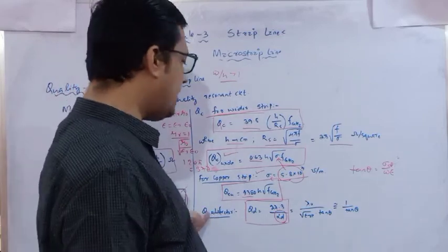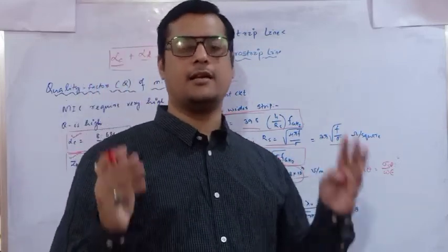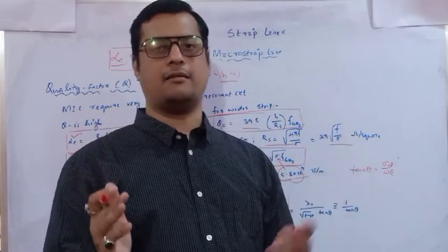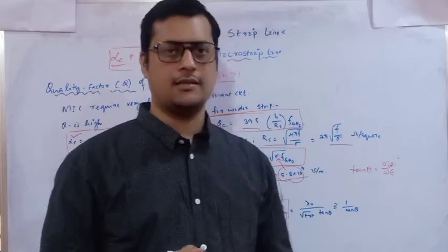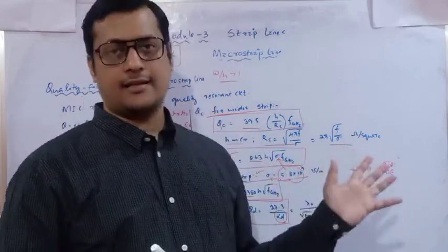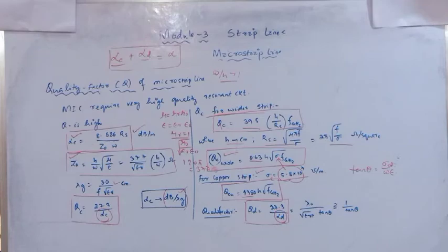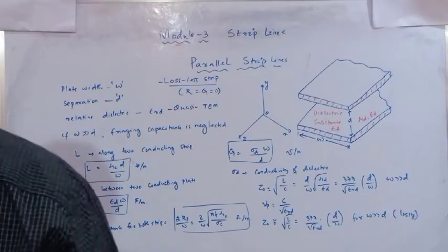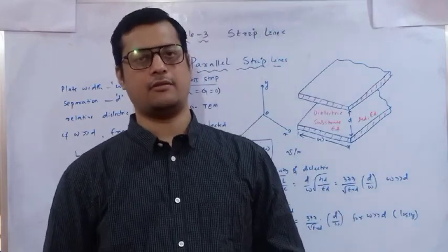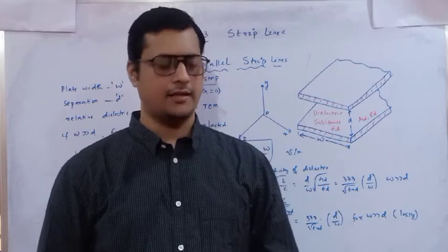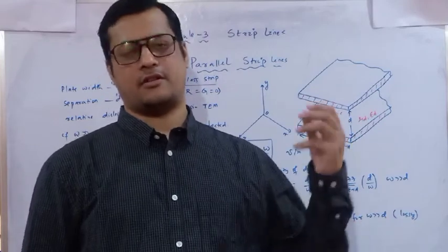Okay, so these are the quality factors for the conductor as well as for the dielectric medium, because we are discussing a microstrip line, which is a combination of a metallic conductor with a substrate and a ground plane. Next we will discuss the different lines and their parameters. For the microstrip line, the parameters we have identified. Next we are going to discuss the parallel lines, because this is also one sort of transmission line which helps to transmit signals.